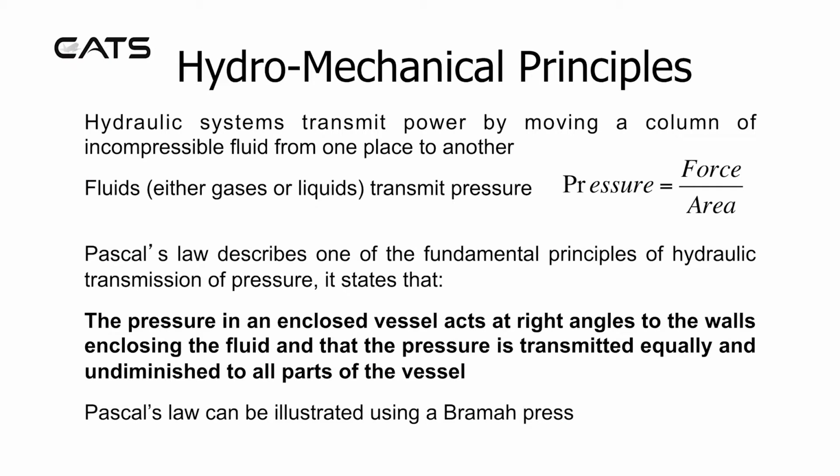Hydromechanical principles. Hydraulic systems transmit power by moving a column of incompressible fluid from one place to another. Fluids, either gases or liquids, transmit pressure. Pressure is equal to force over area. Pascal's law describes one of the fundamental principles of hydraulic transmission of pressure. It states that the pressure in an enclosed vessel acts at right angles to the walls enclosing the fluid, and that the pressure is transmitted equally and undiminished to all parts of the vessel.